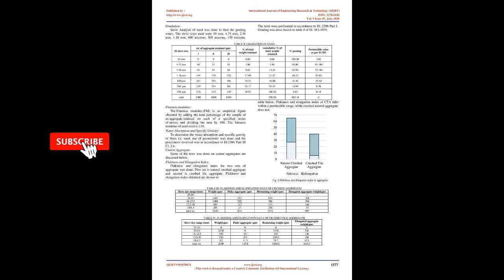The tile produced in different locations and climates may have different physical and mechanical properties. These properties may create a noticeable difference in the quality of concrete produced from these tiles. Also, the different ratio of natural and waste tile aggregate will cause significant difference in results. Not only tile properties but also the natural aggregate properties may cause different results on concrete quality. Different locations and climates have different types of natural aggregates, so the study has to be carried out in different countries for the reliability of the quality of concrete.